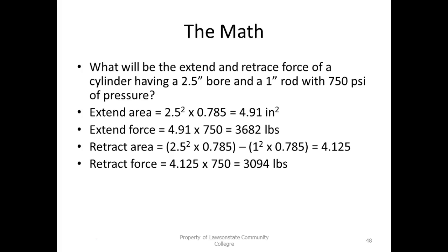If you have to move a weight in two directions, then you have to do your calculations for your rod side, right? You understand, and not your unrodded side. So this is one advantage of a rodless cylinder. A rodless cylinder would generate the same force in both directions.